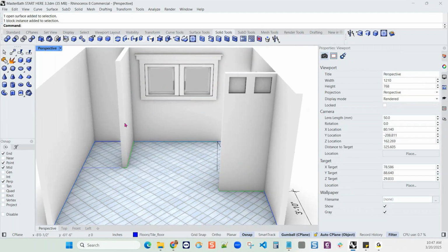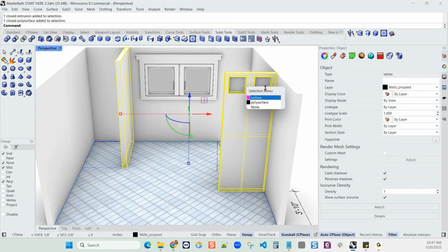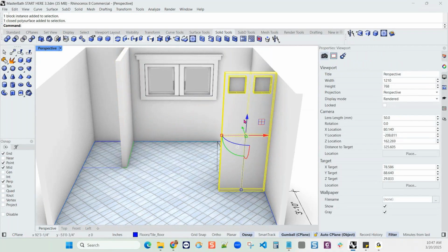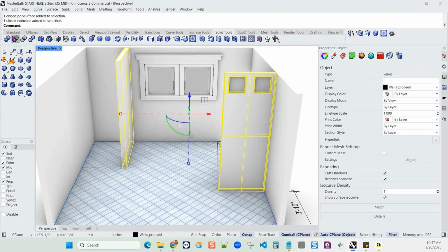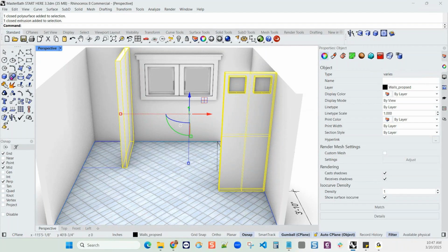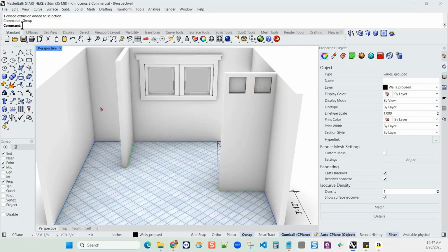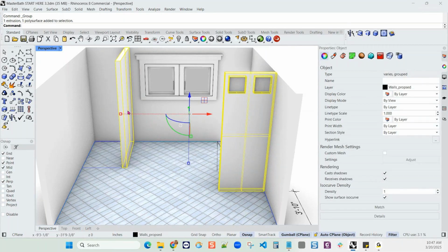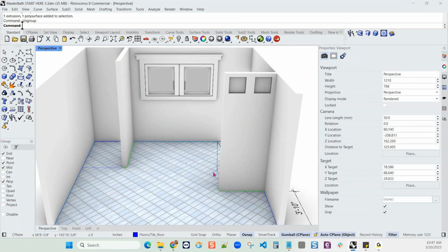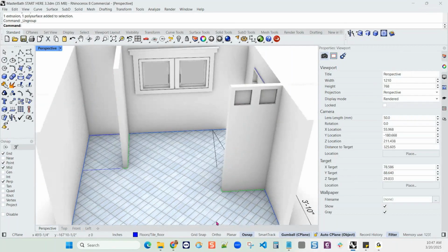Okay, so if I take these 2 walls here, and I can pick the glass to go with it, and I group them together, then I can select them at one time. So that's a group, okay? I can't join those together. They have no common geometry, okay? And then I can ungroup and bring them back out again. So groups are super helpful. They're very fast, but in some cases, like this one here, we wanted to join to make one surface.